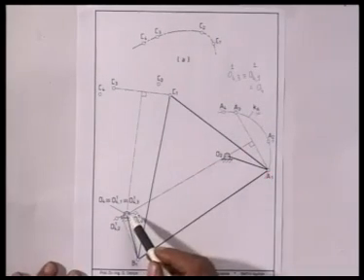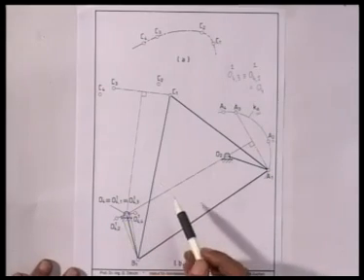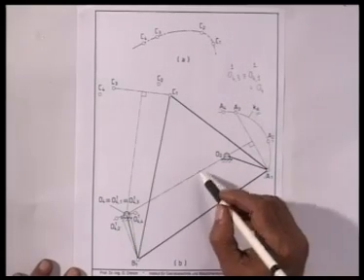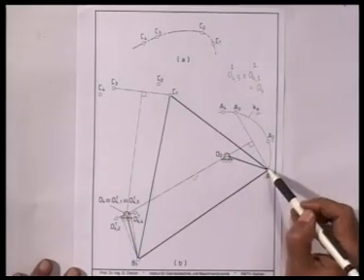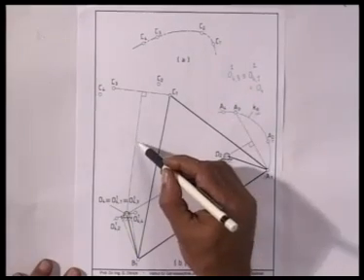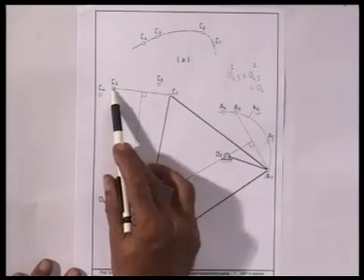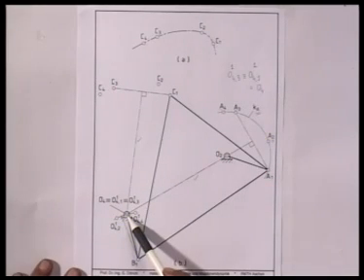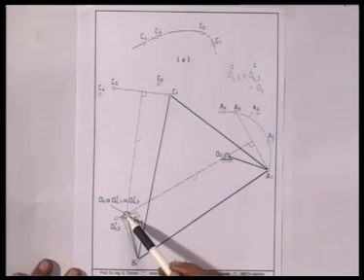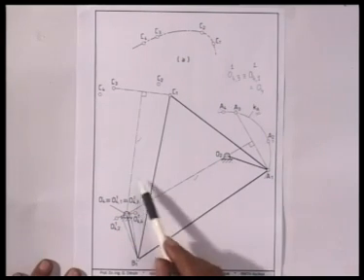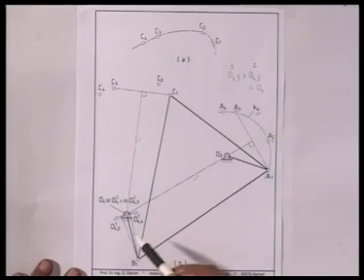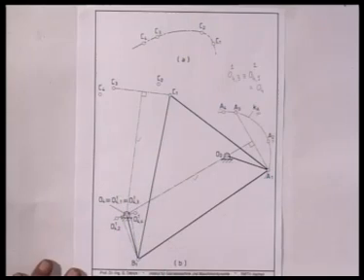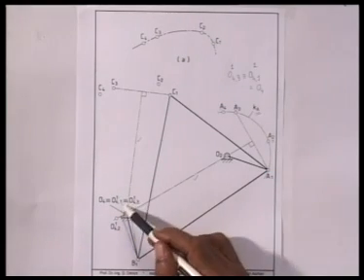Now, O4 is chosen on the mid-normal of C1, C3 and A1, A3. This line is the perpendicular bisector of A1, A3, and this line is the perpendicular bisector of C1, C3. These two lines meet at this point and I choose my O4 here at the intersection of these two perpendicular bisectors. If I choose O4 here, O4 is nothing but O4,1,1. It is very easy to see that O4,3,1 also will be here.